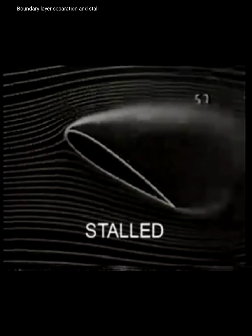Okay, so in this condition, as he said, we took a symmetric airfoil, and we started to increase its angle of attack, or the angle with respect to the upstream flow. At the very beginning, when we had zero angle of attack, we had a region of friction, but as we increase the angle of attack, we change the pressure gradient, and at some point we get separation, and that means that the streamline is no longer able to follow the surface of the body,